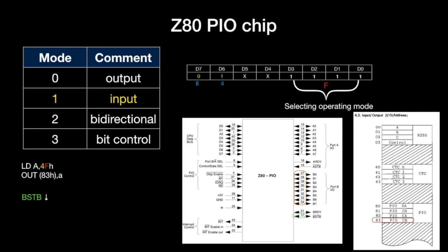When the connected device wants to send data, it will put the strobe signal to low only when the ready signal is high. With the lower strobe, the PIO loads the value immediately, and with the rising edge of the strobe, an interrupt, if enabled, is sent, and the ready signal goes to low. As long as the ready signal is low, the connected device won't send any further data. Now the CPU has to fetch the data from the PIO with the in instruction. After that, the ready line will be put to high again.